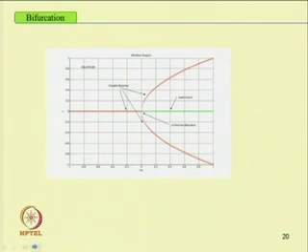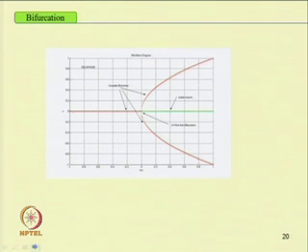Now we know what we mean by a stable system and an unstable system. Also, we have seen some examples of different responses, and in these responses we know what we mean by bifurcation. In case of bifurcation, either the stability of the system changes or the number of responses changes. That means if we have a single branch before, for example in this case, initially we have a single branch, and now we have 2 branches, or we may have 3 branches. At this point, with increase in this frequency, we can see that the number of branches changes. So, this point is a critical or bifurcation point.